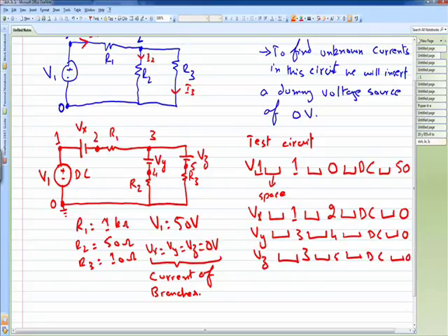Now in the next stage, we are going to define the resistance values. This is very simple. We will be writing R1, which is the name of this resistance, connected between node 2 and 3, and then simply putting the value of this resistance, which is 1000.